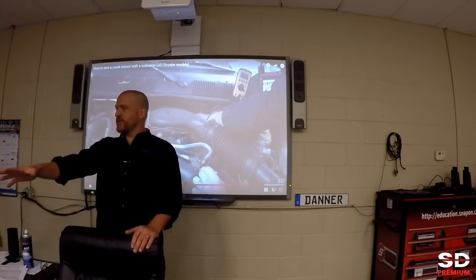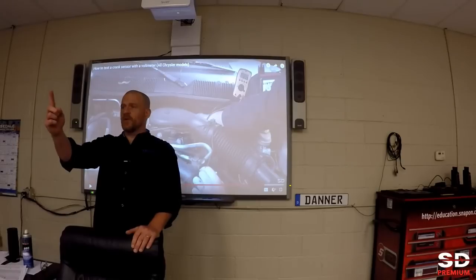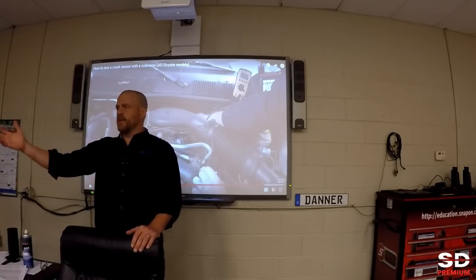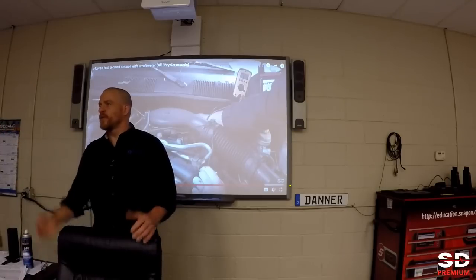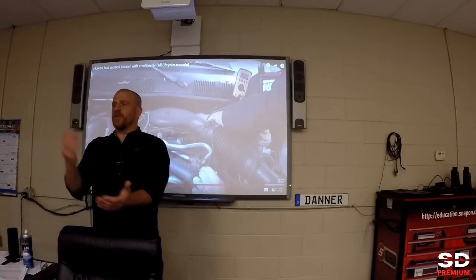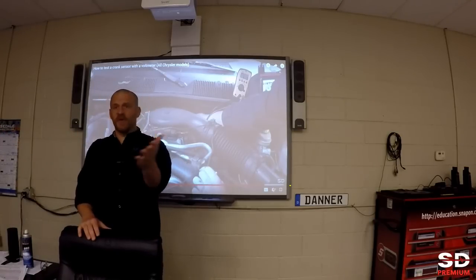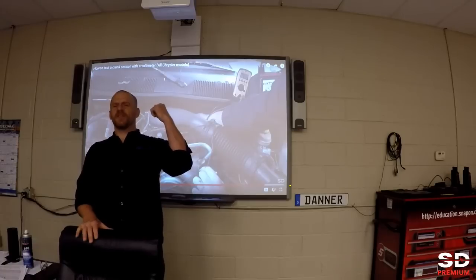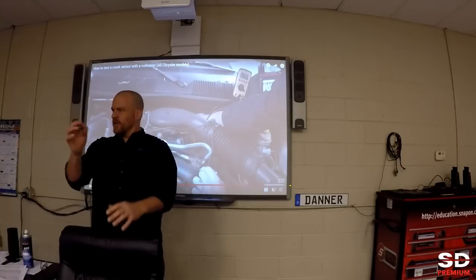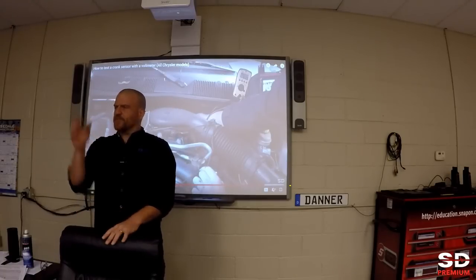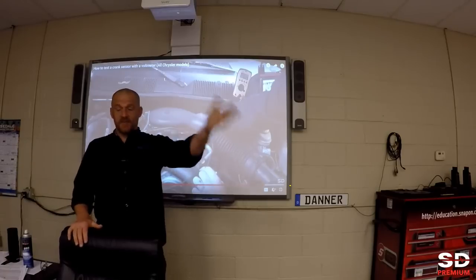This is a distributor design. That was only one coil, so every one of those pulses that we just saw on the crank sensor would do what? What would the computer use that for? Fire the coil, fire the coil, fire the coil, fire the coil. Same coil every time. So did you hear the clicks? What was the clicks? Me touching that circuit, hearing the clicks, and that was spark too.